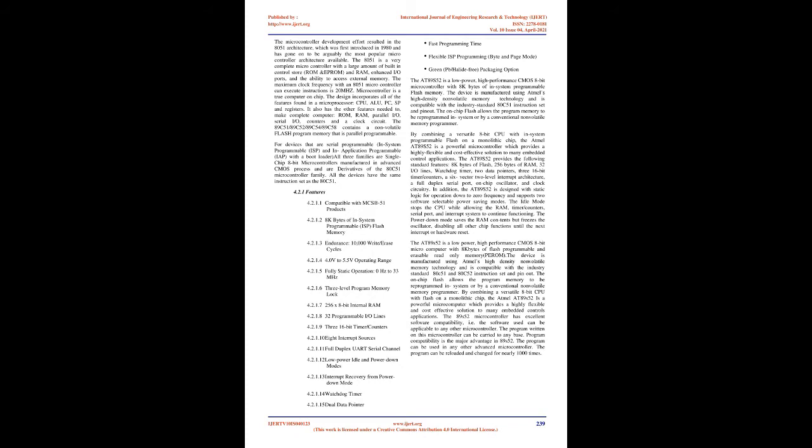4.2.1 Features. 4.2.1.1 Compatible with MCS-51 products. 4.2.1.2 8 KB of in-system programmable, ISP, flash memory. 4.2.1.3 Endurance, 10,000 write/erase cycles.